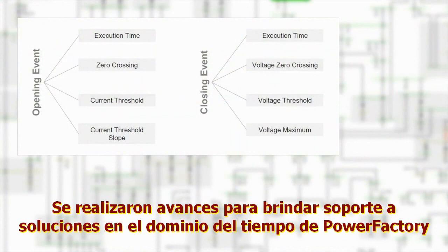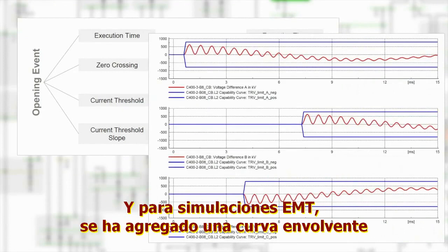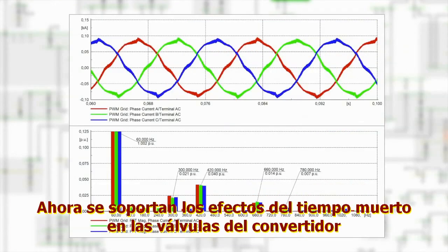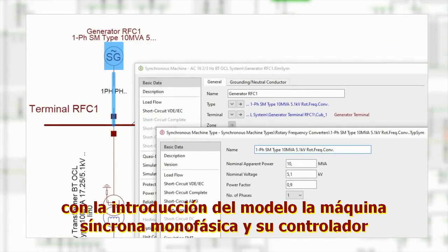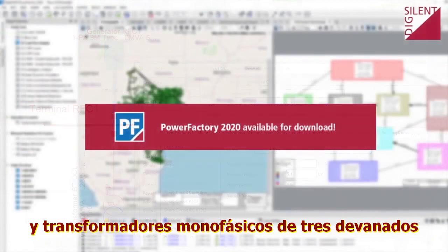Developments made to support time domain solutions in PowerFactory include enhanced switch event options. And for EMT simulations, a circuit breaker transient recovery voltage envelope curve has been introduced. The effects of dead time in the converter valves of a two-level PWM converter are now also supported for EMT calculations. And modeling of single-phase networks is improved with the introduction of a single-phase synchronous machine model and controller and a single-phase 3-winding transformer.